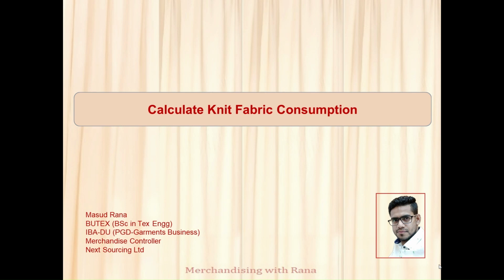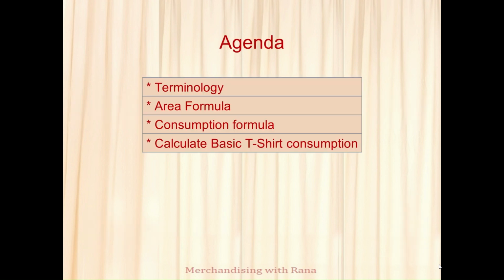Today our topic is how to calculate net fabric consumption. So today we are going to discuss some terminology about the fabric consumption formula, then the area formula, then the regular fabric consumption formula which is traditionally available, and we'll calculate one t-shirt consumption.